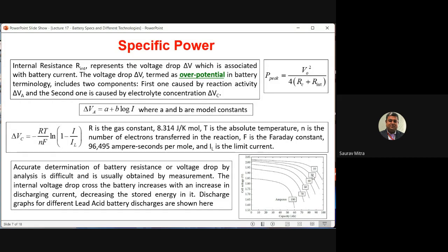If I am saying 20 ampere, you will find that this is giving you less. It is almost 4 or 5 hours that it is giving you good current. After that, it is reducing like that. So this graph, capacity versus cell voltage, you should remember. And you have to always remember that if you are charging the battery too much, if you are pushing the battery too much, you are not going to get the required voltage, because from a lead acid battery we want to get 2.03 volt, and that can only happen if you are drawing 10 to 15 ampere.